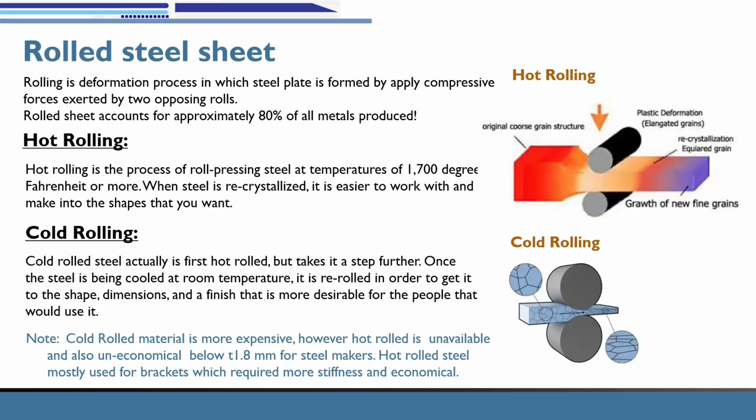Based on the other process, the strength will be defined. This is based on the manufacturing process only, defined into two stages. That I will explain later on. Now we are speaking about the hardened places, where we are using hot roll, like the bumper. In order to get the precise thickness part, we have to go for cold roll sheet. The same for reinforcement, we are using cold rolled only. Reinforcement needs to be strong, sir.